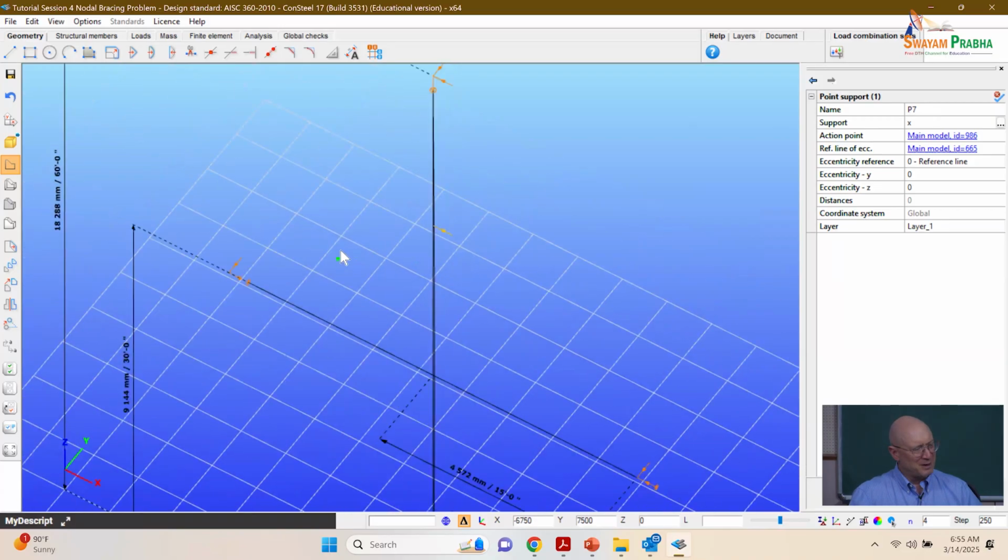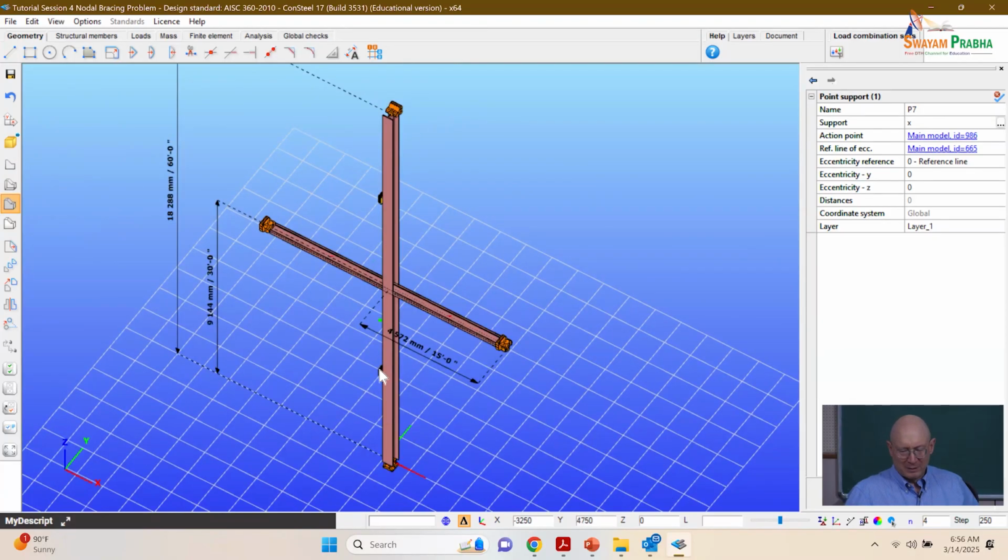So remember, we have a situation like this, we might need to worry about torsional bracing or torsional buckling, right? Again, we're spanning 60 feet, except we're grabbing the middle of this, and it's major axis bending in and out of, or normal to, this wall of the shaft. Our flying beam is in major axis bending to try to provide support to the middle of the column.